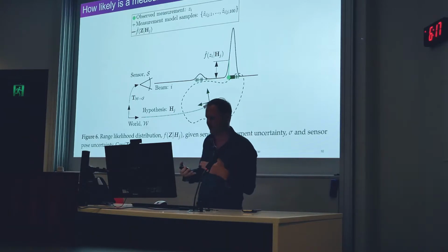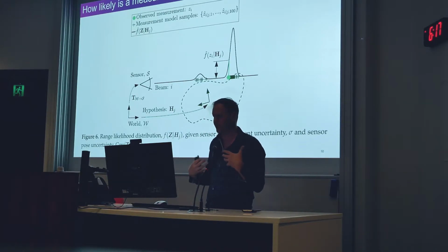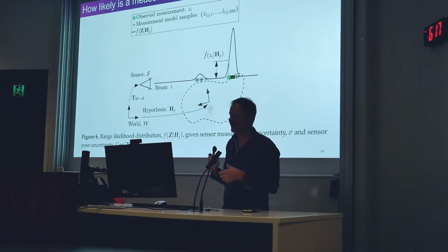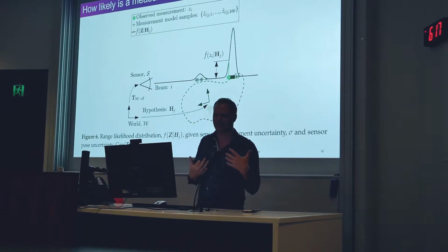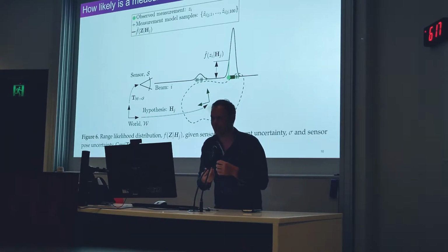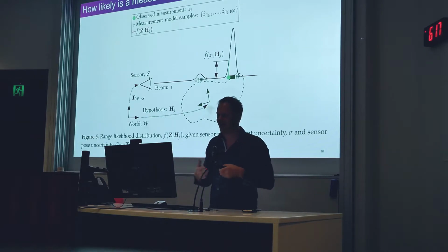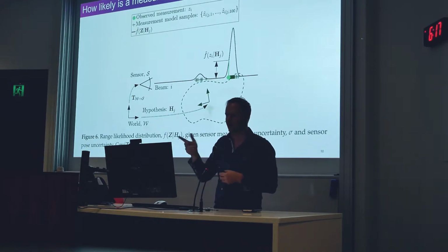When I install LiDARs on big bulldozers and rope shovels and drag lines and all sorts of things, I can't tell you within an inch where that sensor is, even with survey gear and all the best stuff in the world. So the bigger the machine, the bigger the uncertainty. Can't measure through the machine's walls to find its origin that doesn't exist. It's not like playing with a CAD model. So I've got some uncertainty, typically a few centimetres and maybe 10 to 20 milliradians on the XYZ roll pitch yaw of the sensor.